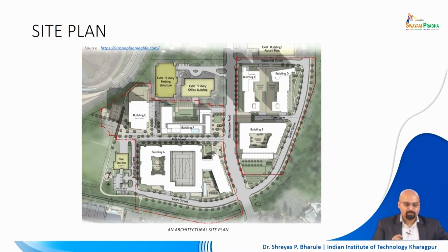Now, a complete site layout or a complete site plan would ideally look something like this. In the site layout you will have multiple buildings. For example, consider this particular site layout as a large layout which is being proposed for a particular area. You will have multiple buildings all marked in white, which are the proposals, and you will have the hatched or colored buildings, which are already existing. Along with that, all the vegetation, all the different kinds of trees which are being added to the site will be mentioned, as we talked about earlier.